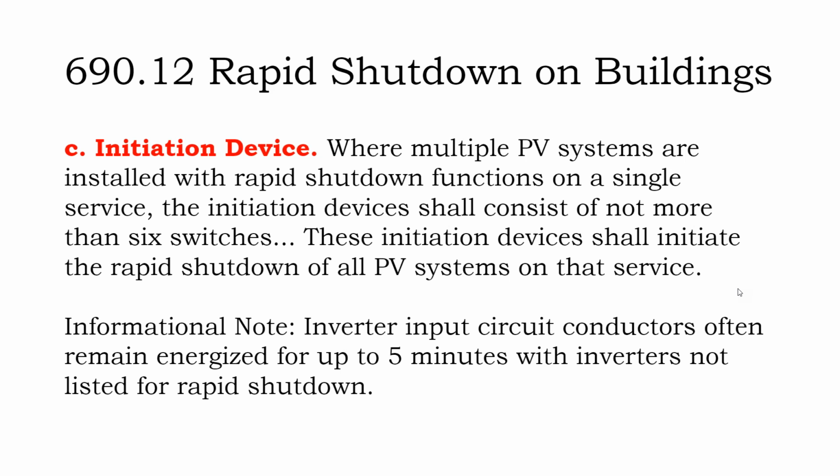it makes a note that says when you turn off a solar array that does not have dedicated circuitry for taking the isolated electricity that's still up in the solar array and draining it out of the conductors, that electricity stays in the conductors, and it can stay in those conductors for up to 5 minutes if there's no grounded circuit that is being activated to drain that voltage to ground.